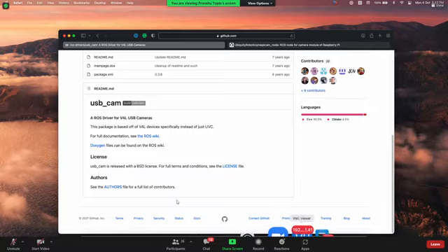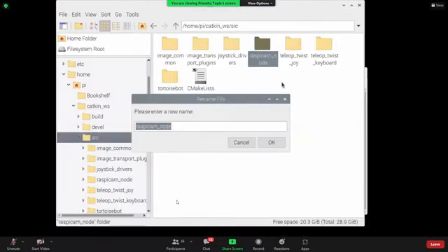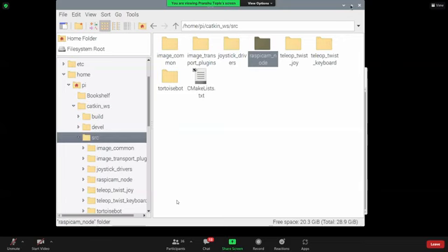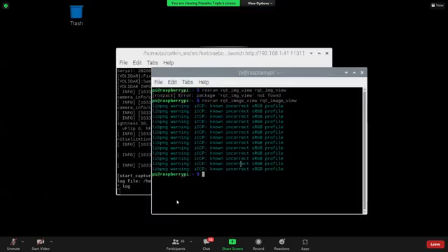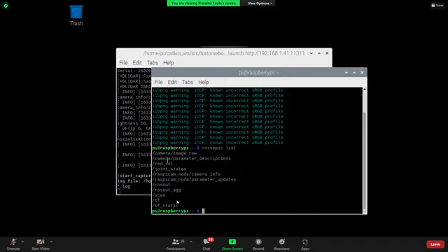Now we have our camera working using this Raspberry camera node. If I run rostopic list, we are getting a topic which is camera image raw. This is the raw image from the camera, but we want to process this raw image. So how to process it?